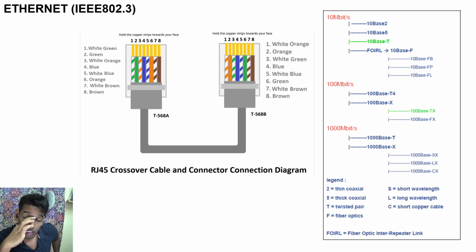So you might have seen this RJ45 cabling being used in your substation. When you see an RJ45 cable, a beginner might think that it is universal, in the sense that if it is RJ45, it is Ethernet. That is a misconception. Ethernet has been developing for so long that inside Ethernet there are a lot of different speed classifications, like 10 megabit Ethernet, 100 megabit Ethernet, 1000 megabit Ethernet.